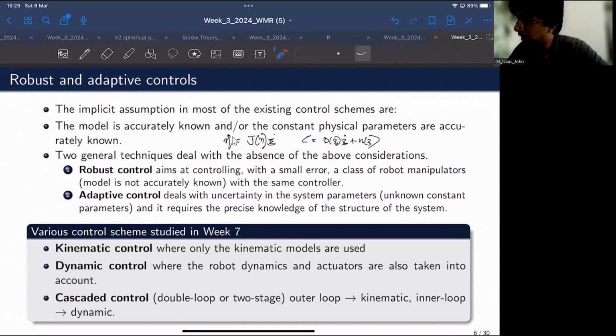And as you can recall, the constituent elements of the mass matrix, or this inertia matrix, consist of parameters such as the center of mass of the robot chassis and the mass moment of inertia about the vertical z-axis. So unless you exactly estimate what this mass and moment of inertia are, you cannot claim that you have accurately modeled the robotic system. And because of various issues, there could be some deviations between the estimated value and the true value.